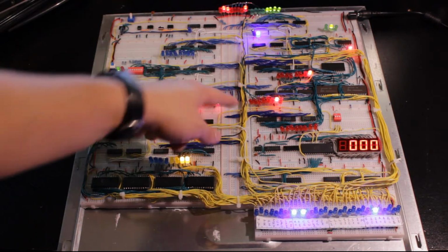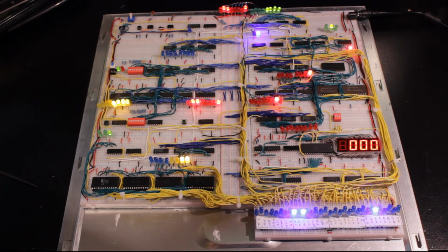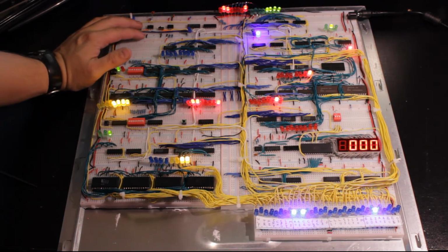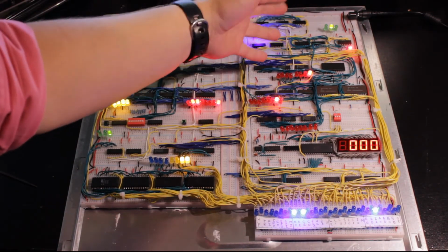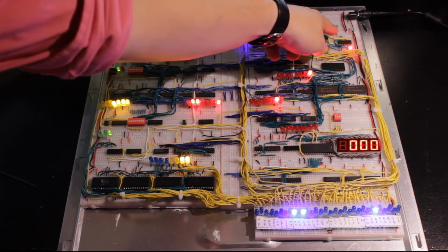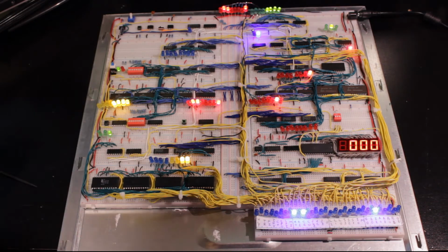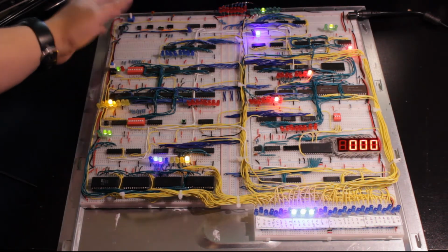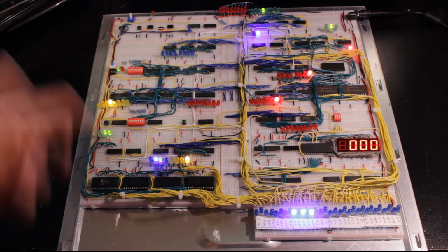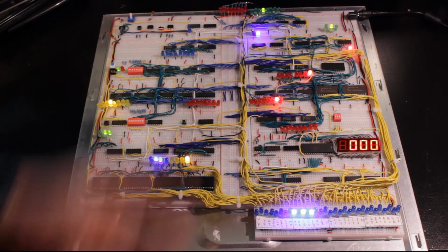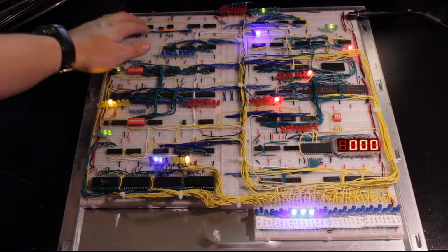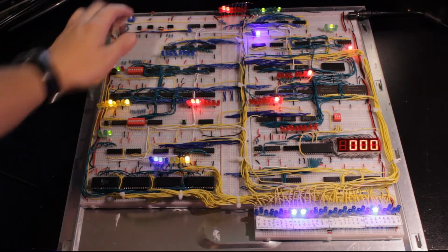We see jump less than 0 here in memory index 0xF. Now we're not less than 0, so as we can see we have the flags, which are sign flag, carry flag, and zero flag, and the zero flag is off, so we're not going to jump. We're just going to go right through this, fetch the location where we would have jumped to, do a conditional jump, but we can see our jump LED, which is inverted, is still on, so we're not jumping. Keep going through, fetch cycle for the next instruction,